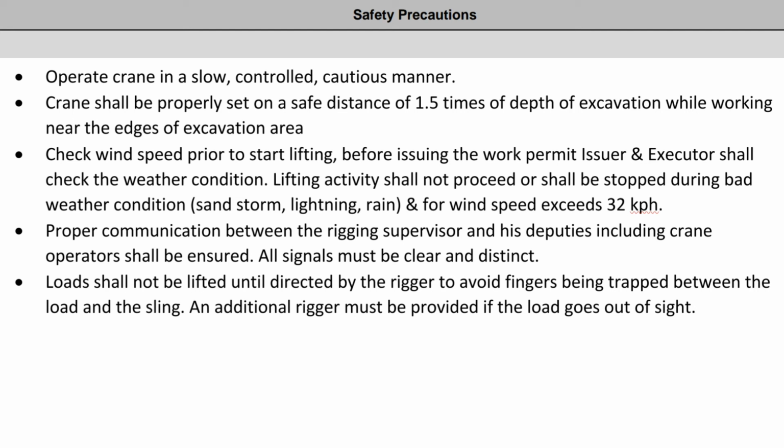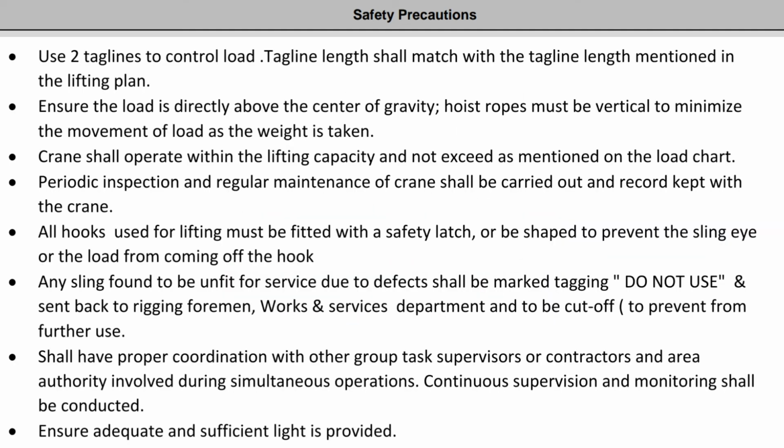Proper communication between the rigging supervisor and his deputies, including crane operators, shall be ensured. All signals must be clear and distinct. Loads shall not be lifted until directed by the rigger to avoid fingers being trapped between the load and the sling. An additional rigger must be provided if the load goes out of sight. Use 2 taglines to control the load. Tagline length shall match the tagline length mentioned in the lifting plan.